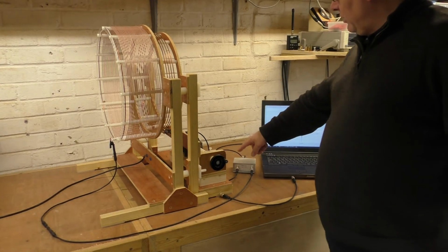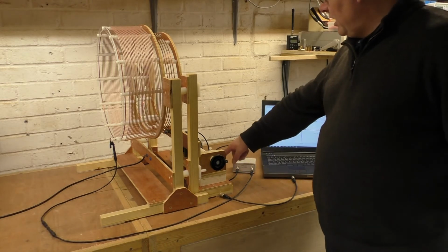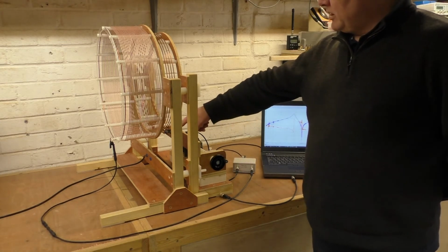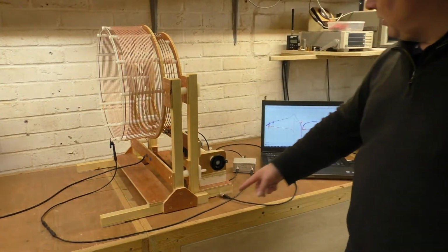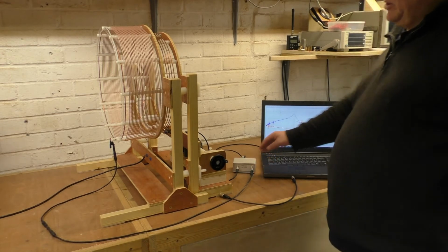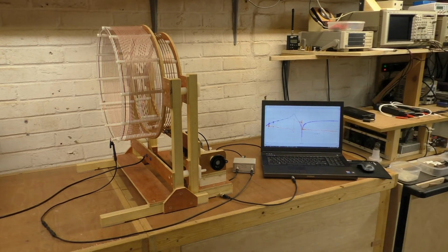This time we're going to take a look at S21, which is the input to the system. It goes through, and then we're going to pick up what comes from the output, and feed that back to the input. And that's officially S21. Now, because it's a gain or transmission from the input to the output, we're not going to use impedance there. We're going to look at that in decibels.